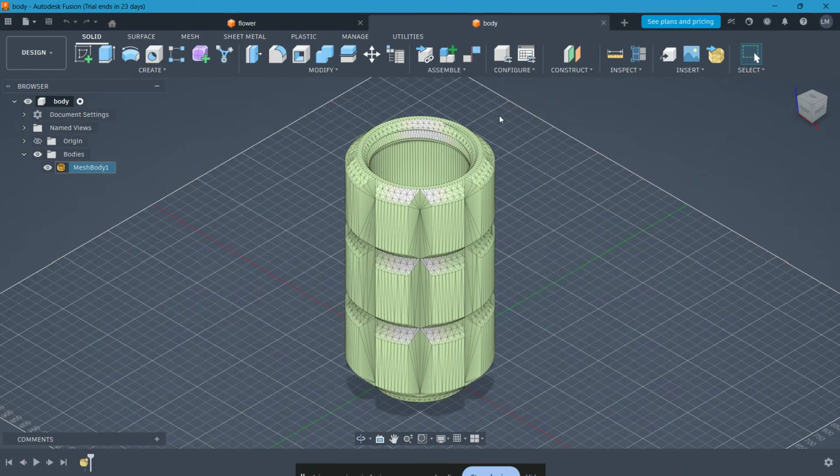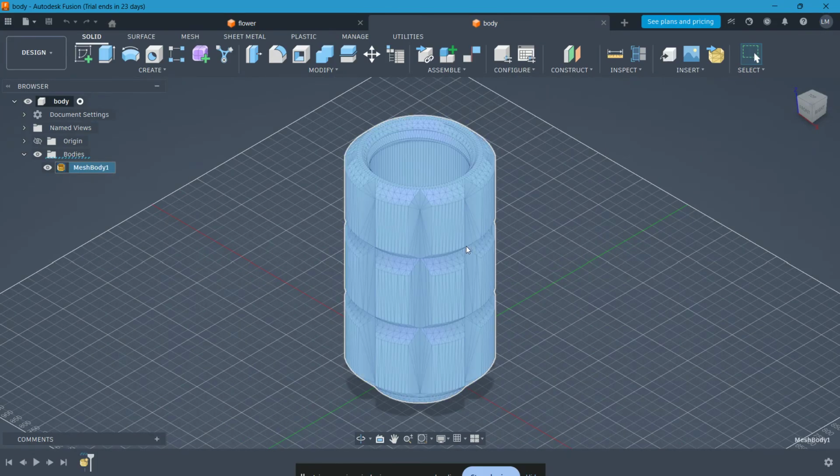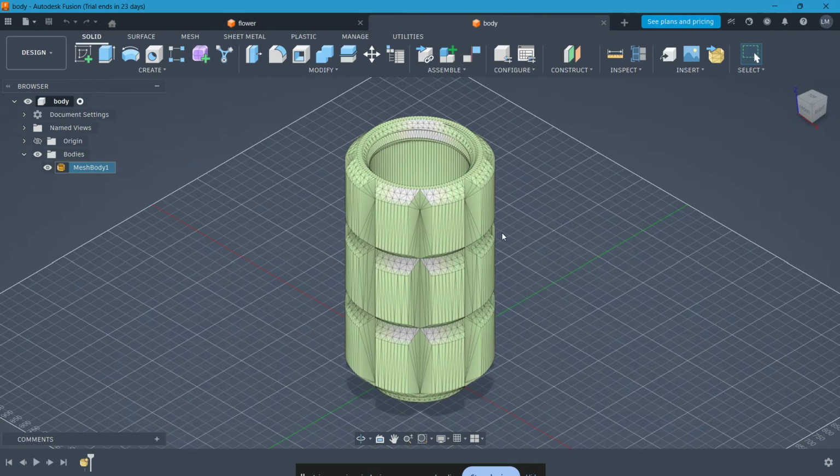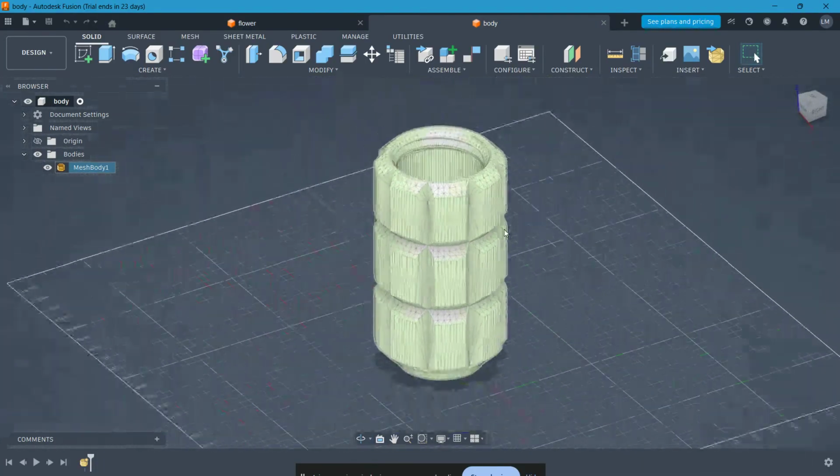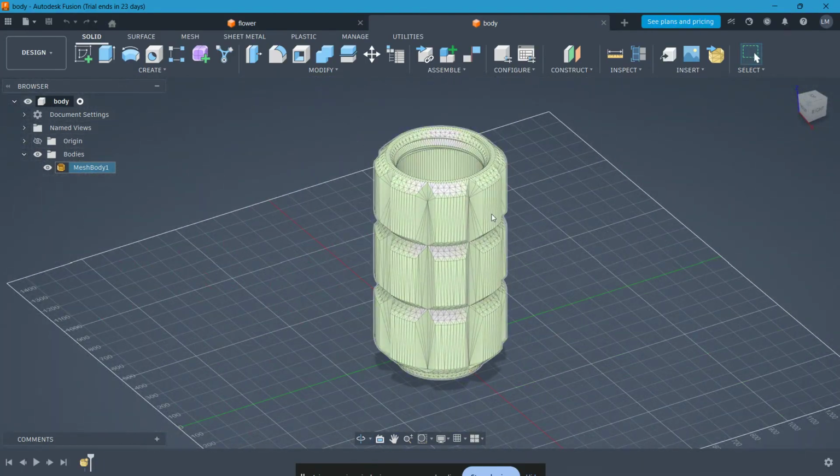Alright, let's jump right in. First, let's quickly understand why this error happens. A self-intersection error appears when parts of the model overlap or intersect with each other. For example, two faces might be cutting through each other without you noticing, especially in complex designs.